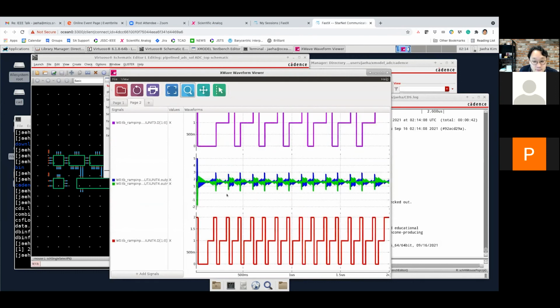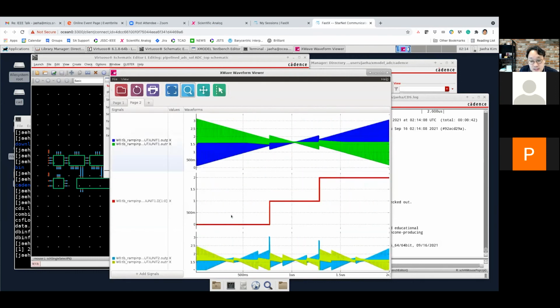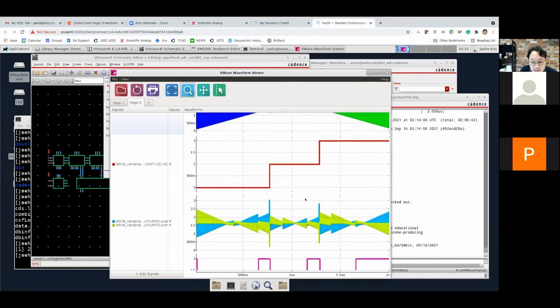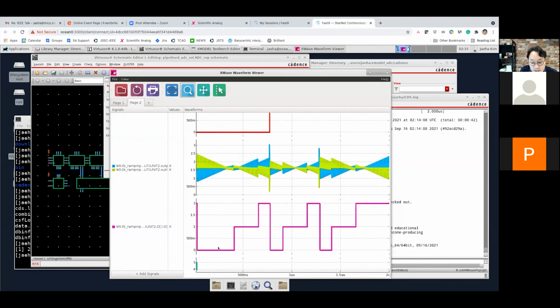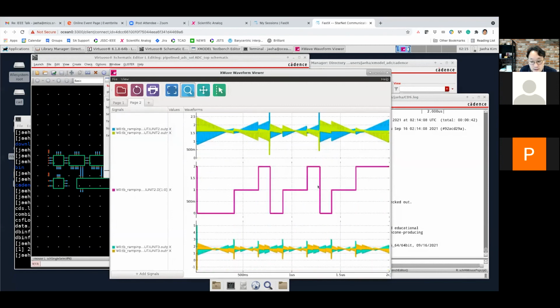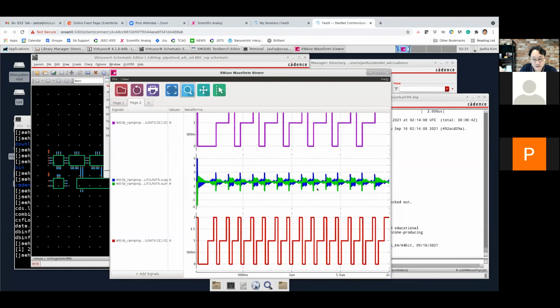And these are the waveforms for the intermediate stages. For the first stage, the code is gradually increasing, and these are the residual outputs propagating to the second stage. In the second stage, you see the codes going through these patterns because now there are lower significant digits. And you see those patterns having shorter periods over time because they're toggling more frequently.